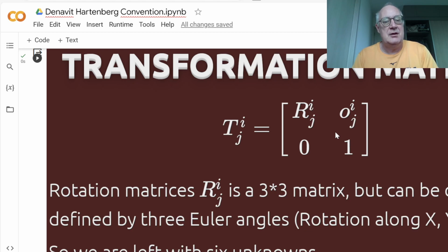In order to derive the rotation matrix, you need to also fix an order in which you do the rotations. If you have a coordinate system and you rotate around x, then y, then z, which is one popular way of describing the Euler angles, you get a different result than if you rotate by y, then z, then x, for example.